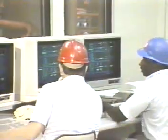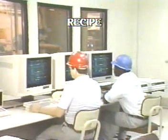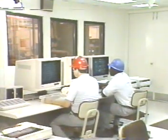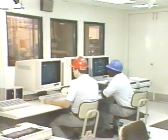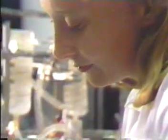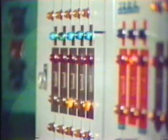Batch processes generally have specific recipes for each product. Control is designed to implement a particular recipe, but because of the flexibility of the instrumentation, the same process equipment can often be used to produce many different products or product grades. Control in a continuous process, on the other hand, is designed to maintain stability of a process and of product quality, despite changes in process conditions.